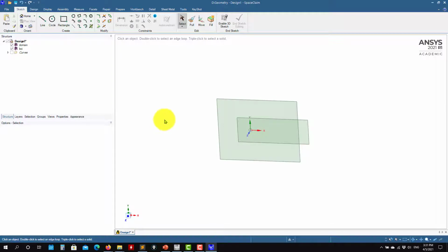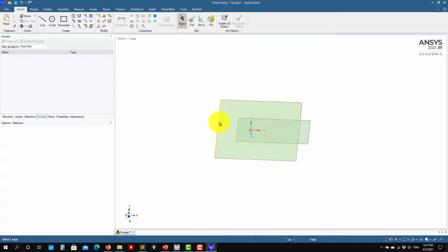But let me create here also the solid. So see that we have the surfaces here. Okay, so let me close it here. So let's work with this one, the 2D. Then I show you the option for the 3D. So this is all when it comes to this. Remember also in groups, here you can add the boundary conditions as you want. You select the edge and put it, or you do it directly in the meshing stage. Okay, as I mentioned, I like to do it at the meshing, but it does not make any difference, honestly.